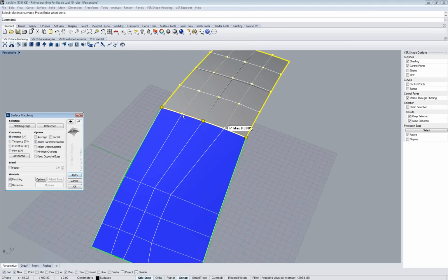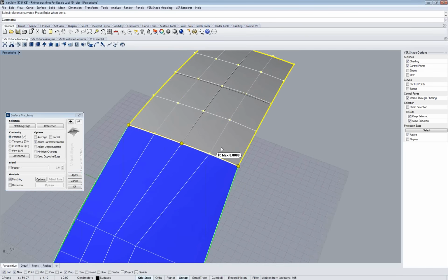And doing so, it then moves the control points of the matching surface so they go over onto the right position into the reference surfaces, usually achieving a better transition quality. This is what adopt is doing. So it takes care of the control point distribution of the reference. While adapt also says, okay, not only take care of the distribution, but also raise your degree and the number of spans to the one of the reference, so you can make sure you get a perfect transition, because every control point on the matching surface is matching to a control point on the reference.